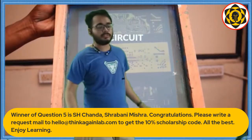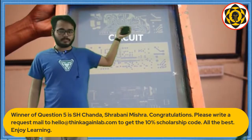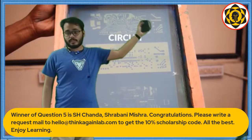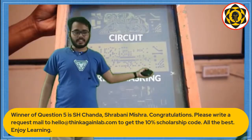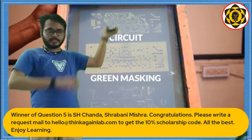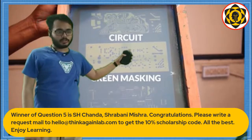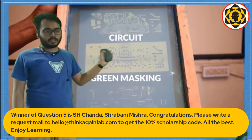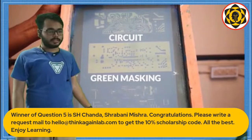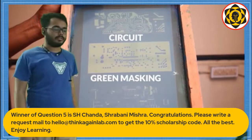Now since we are doing the screen printing, let's focus a bit on the screen. So this is the circuit. These are the traces that will be printed on the copper. Next is the green masking. This is the top masking that will prevent this circuit from getting accessed in unwanted places, and it will only allow these small designated solder spots for the circuit to access. And finally, there is this legend. Legend is basically the silk screen that will have all the writings and stuff like that.